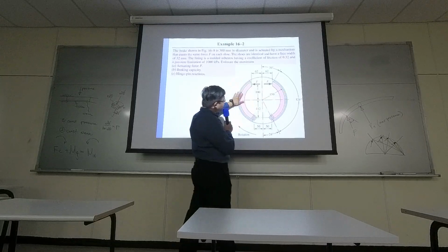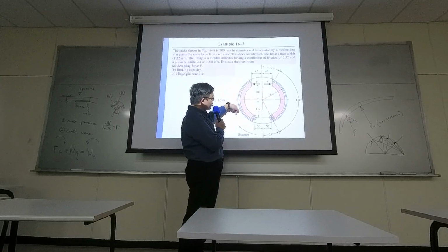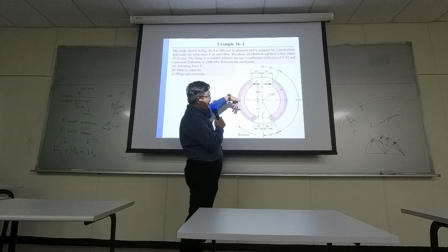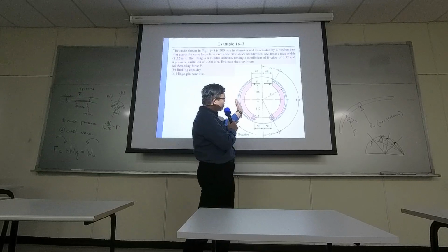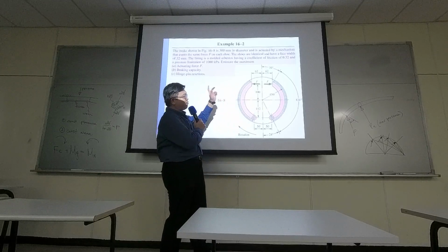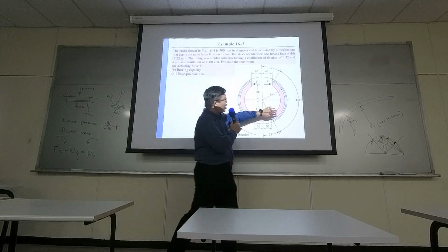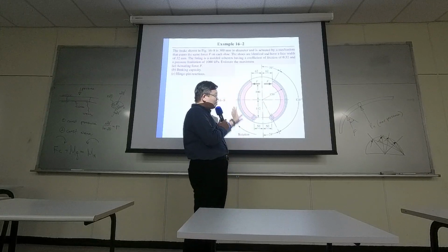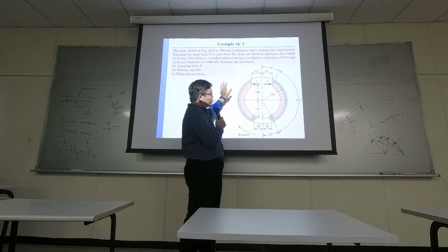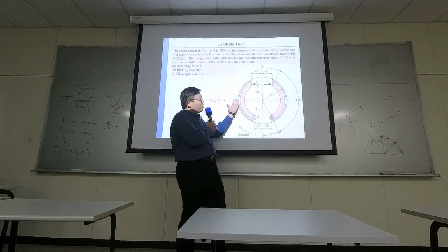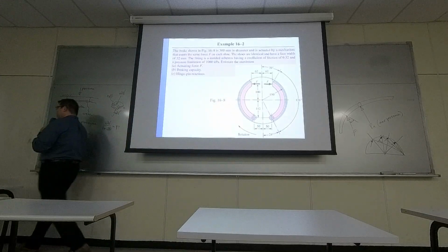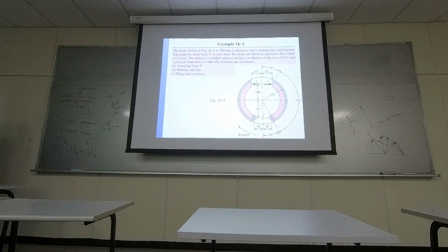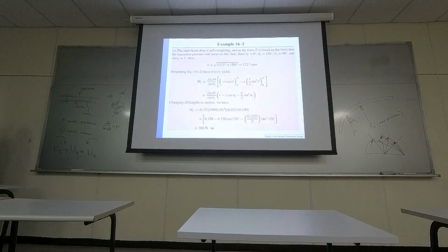But for the left hand side, it's also going counterclockwise. So even though the geometry is symmetric, the friction force is always fighting against the geometry. So if you directly mirror the math, the friction force are following the different direction. I think that's the difference.